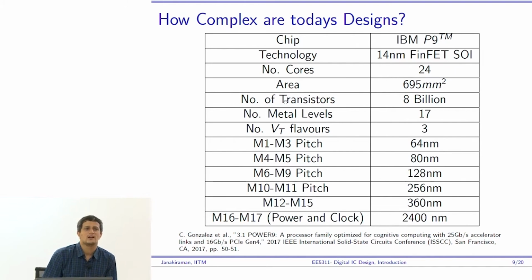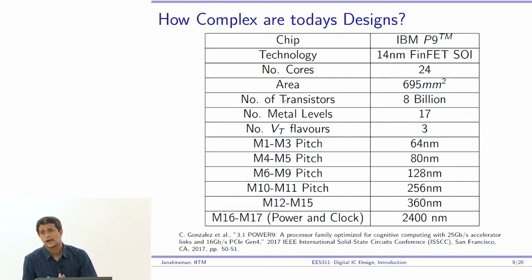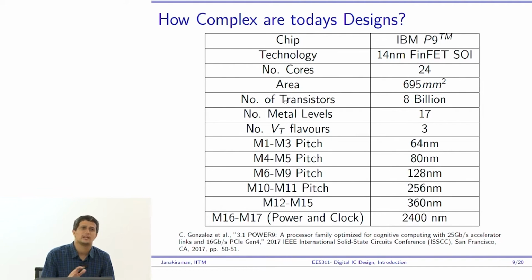In 14 nanometer, to handle leakage current, you had to go to a radically new technology, okay, which also makes technology development very expensive, by the way. Okay, the number of fabs have come down to a very small number because it's not profitable for anyone and everyone to just run a fab these days. The investment you have to make in technology to get that small gain of performance or power is extremely high. It was not that high about a couple of generations ago. Coming from 90 to 65 or 65 to 45, not much of a difference, but now it is very expensive, okay?